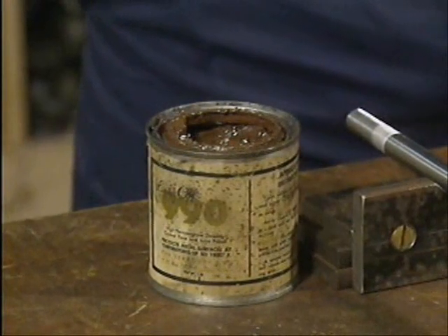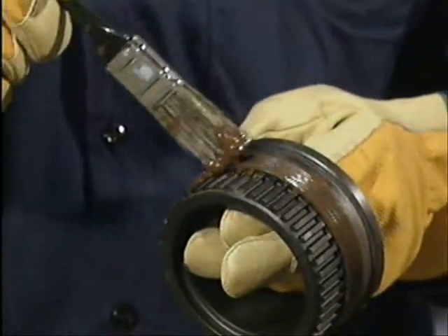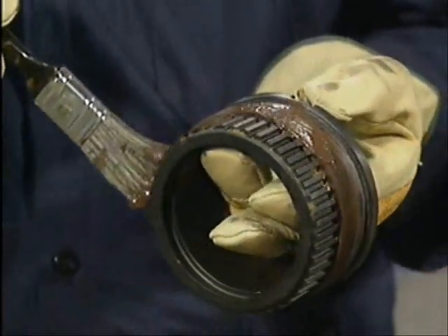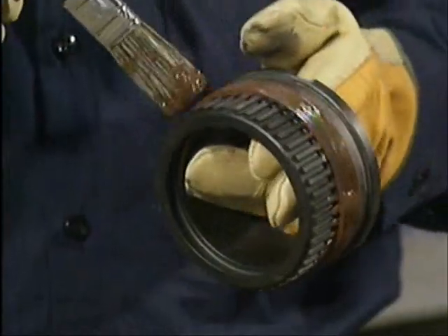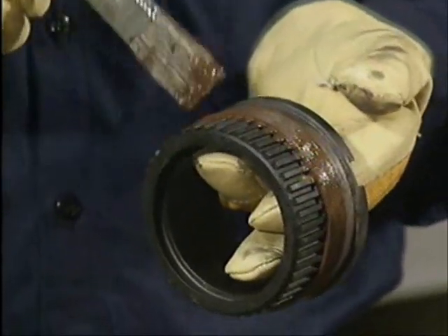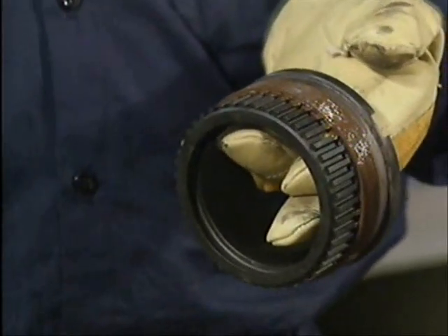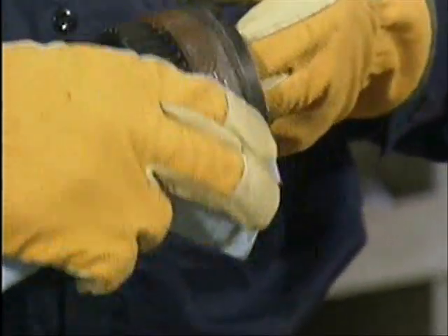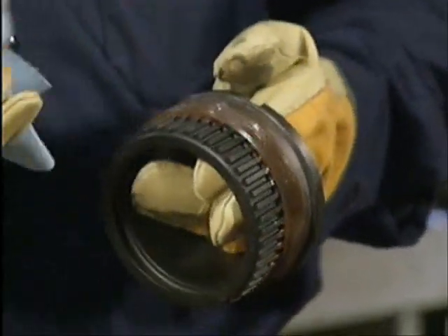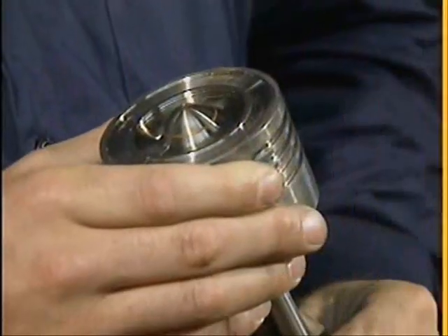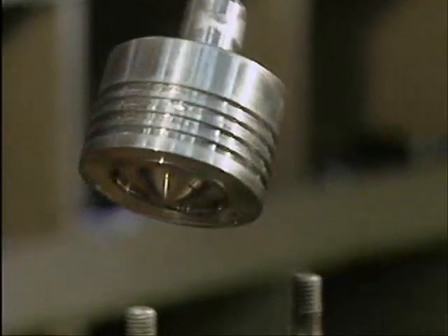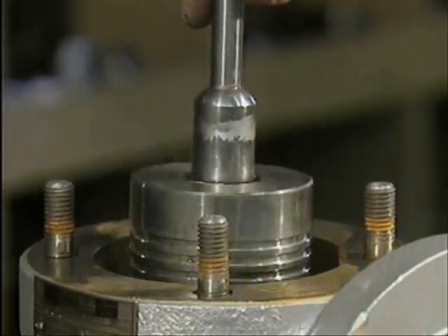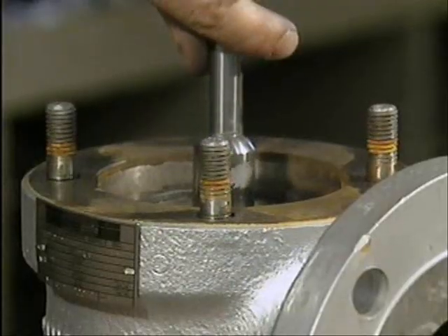Lubrication is also an important part of reassembling a safety valve. You should follow the valve manufacturer's specifications for the exact type of lubricant and the method you should use to apply it. Typically, an anti-seizing compound is used to lubricate threaded surfaces so they won't stick together or seize as a result of temperature changes during valve operation. Also, during reassembly, it's absolutely critical that the disc and the valve seat make perfect contact so steam can't leak through the valve.